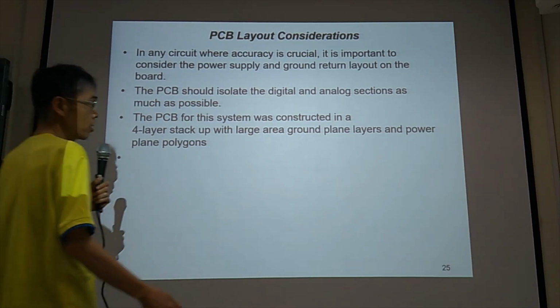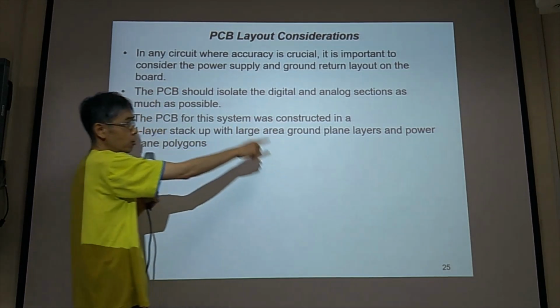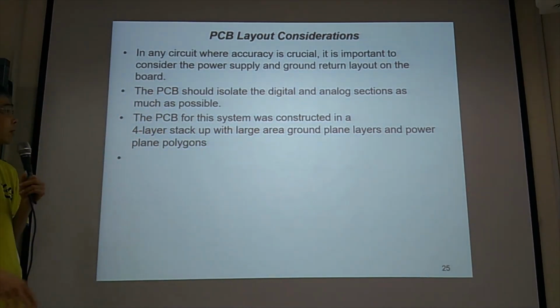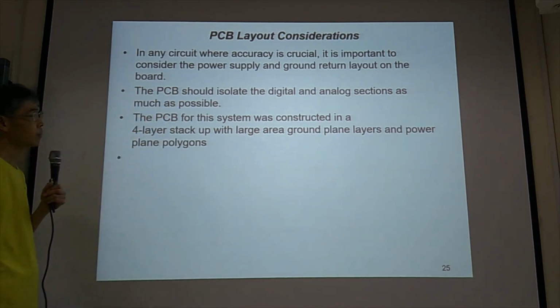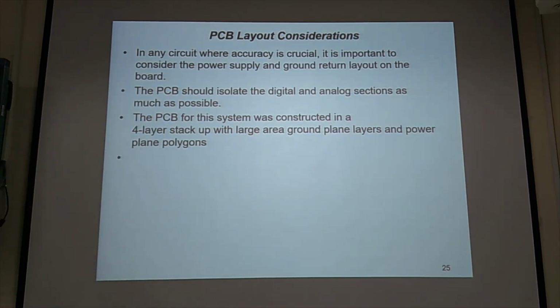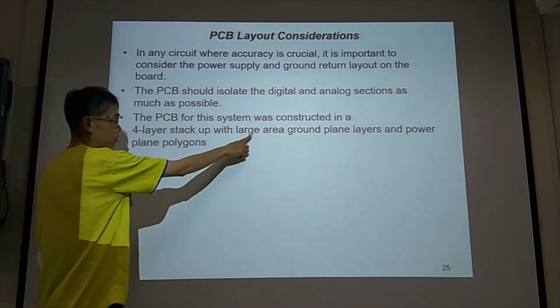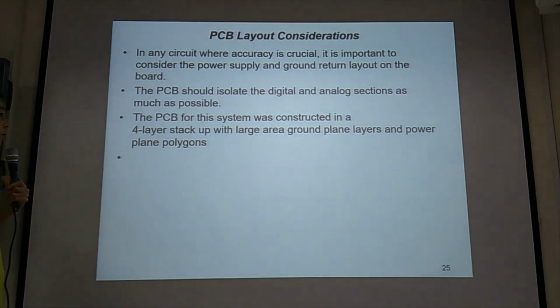Like in your circuit, you have digital circuit, you have analog circuit. You need to separate them as far as possible. So this is one thing. Then PCB board, the large ground plane, and power supply and ground return layout on the board.